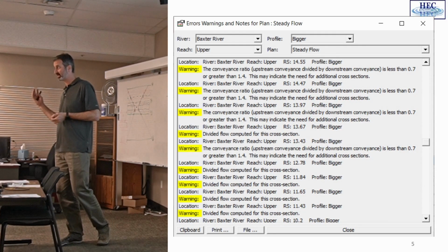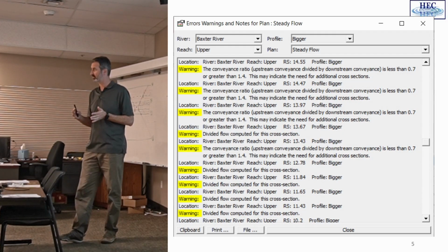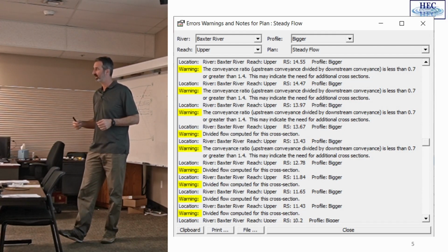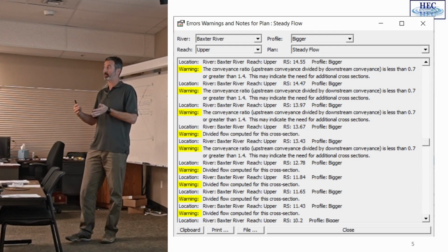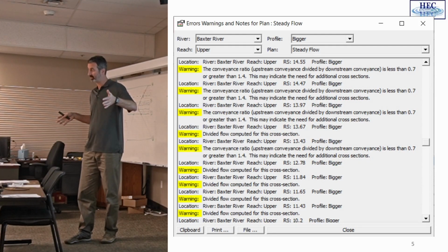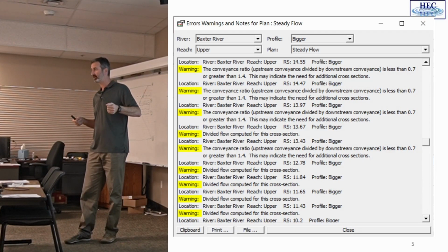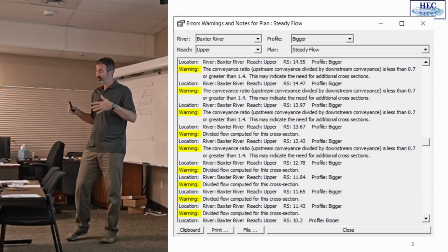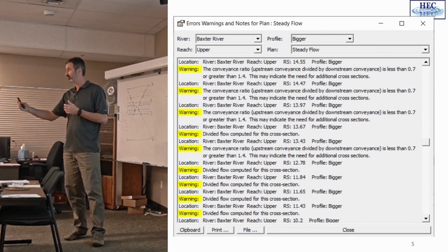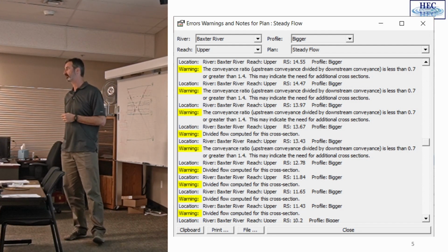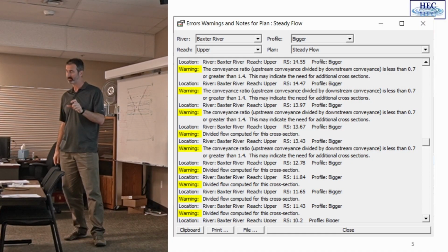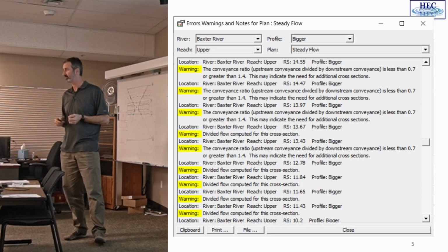On bigger rivers like the Mississippi, then they end up being closer than that because the Mississippi River is miles wide. And you want cross sections maybe only a mile apart. Meanwhile, it's 3 miles wide. So the cross sections would be less than the width of the river. And you can get away with the cross section spacing being, anyway, that's the ratio I'd like to look at, is the width of the channel, a couple times bigger than that, a couple times smaller, or half fractions of that seem like a good way to do that.